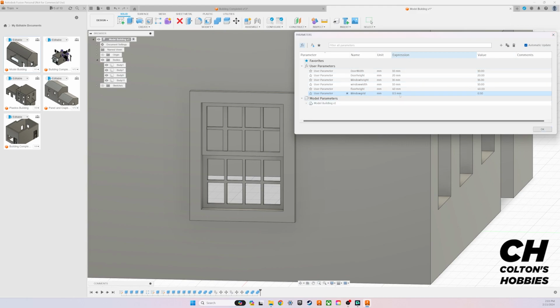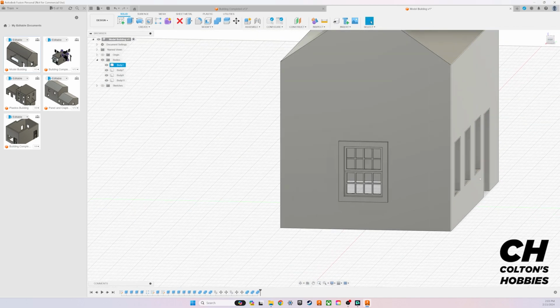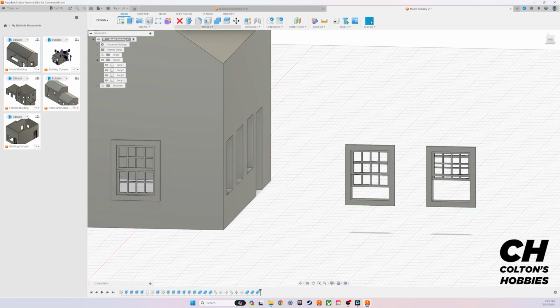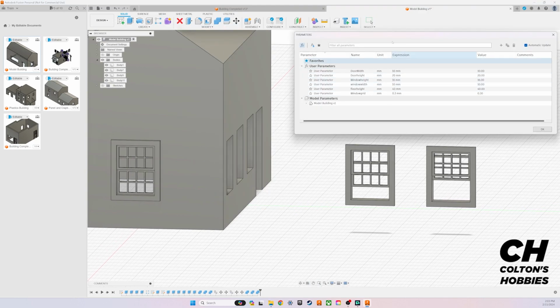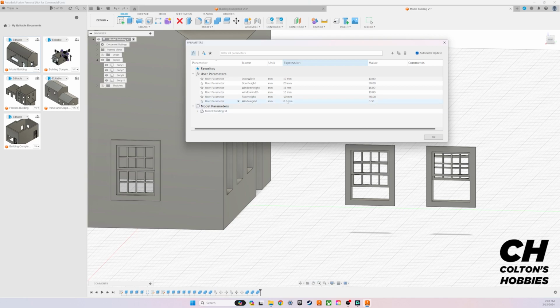I think that's the part that has sold me on it compared to other places. So if you want to double check or change the window grid back, you do have to click off of it, just so you know, to click back to it. But 0.3, enter, and our window is done. And I believe if we go to modify and change parameters, because those were copies, it may actually adjust those as well. So let's change this to 0.5. And as you can tell, even the copies.